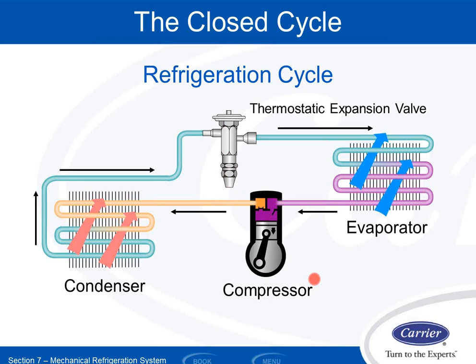The compressor has one main fundamental job in life. His job is solely to change the pressure of the refrigerant, to increase the pressure of the refrigerant. So it comes in at a certain pressure, he's going to step it up to a higher pressure. I said before, if I increase the pressure of refrigerant in a closed volume system like this, the temperature has to go up, right? Because PV equals nRT. So if I increase the pressure and the volume stays fixed, temperature has to go up.